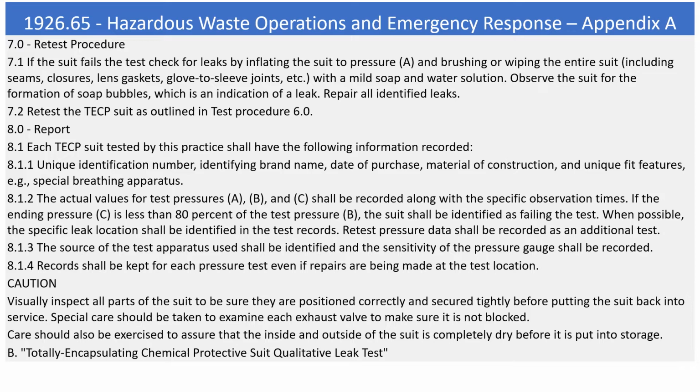Caution: visually inspect all parts of the suit to be sure they are positioned correctly and secured tightly before putting the suit back into service. Special care should be taken to examine each exhaust valve to make sure it is not blocked. Care should also be exercised to assure that the inside and outside of the suit is completely dry before it is put into storage.